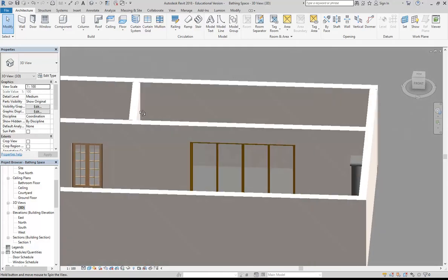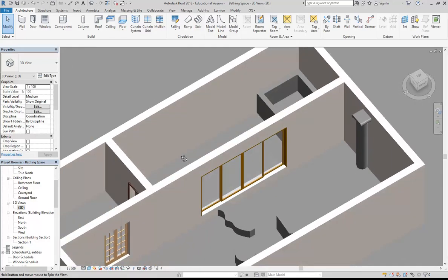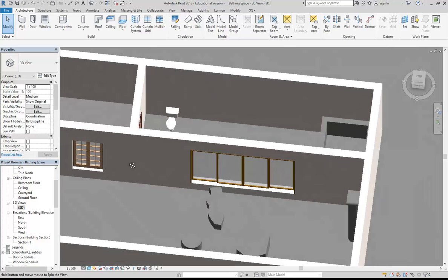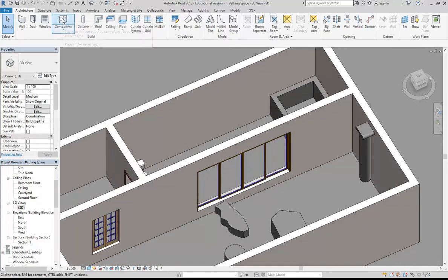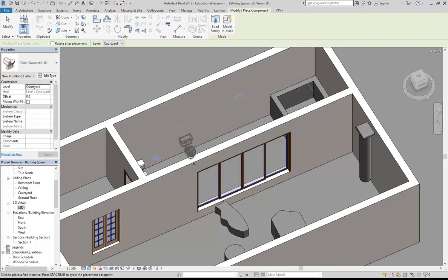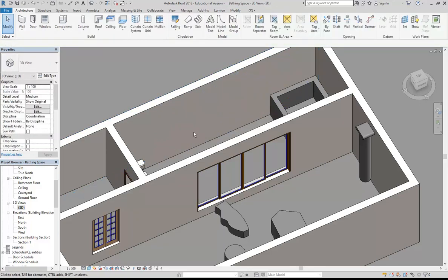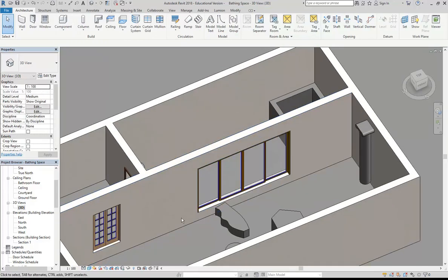But yeah, make sure you have a go at putting in some, at least some doors from the library, and then if you get that done, try and get some other families and just spend some time experimenting and seeing what you find in the library with those different tools, doors, windows as well. Try some windows if you can, and don't forget about using place a component, like you did to get the WC or the toilet, and you know, you can always see if you can find some sinks and some other things that make sense in a bathroom. See how you go.